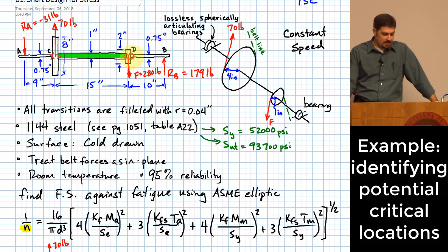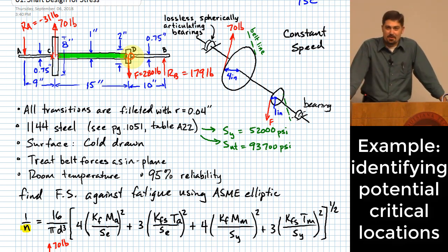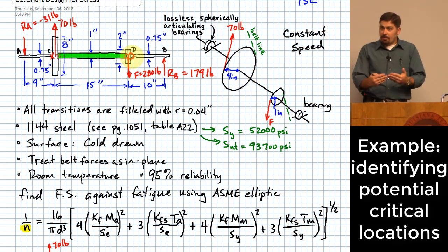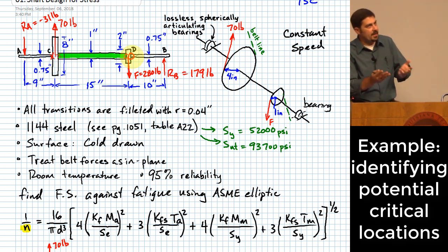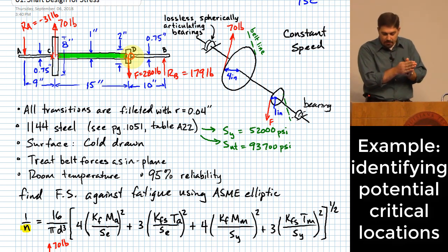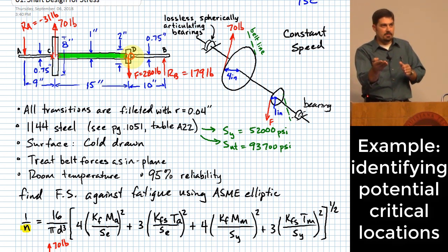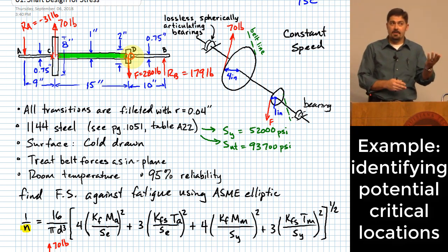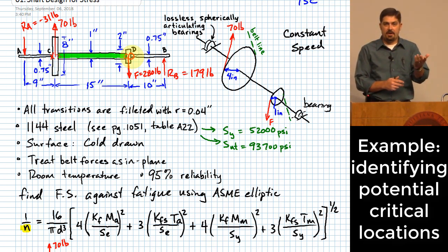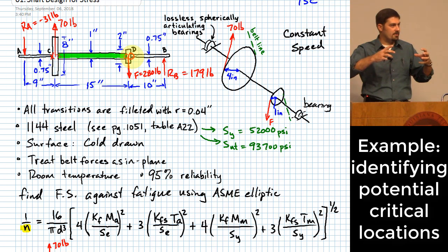Okay. And the answer isn't necessarily yes or no, right? I'm not saying that you should be able to say yes or no just yet. Okay, let's think about it. They carry the same amount of bending moment between those two locations, right? So there's that. But then one of them is smaller, right? But the one that's smaller is not carrying torsion. So there's the bigger one, but not only does it have to carry the flexure because of the bending moment, it also has to carry the torsion down the axis of this part, right?